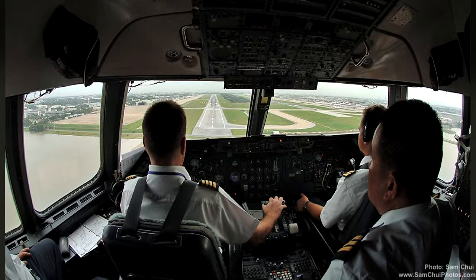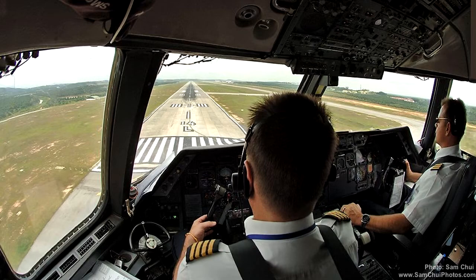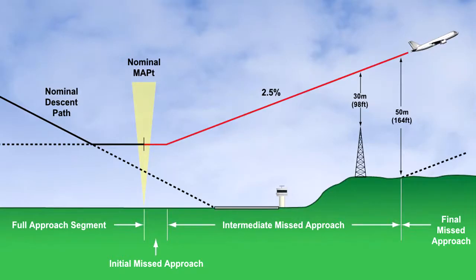In the event of loss of glide path during the final approach on an ILS precision approach, the approach will become a non-precision approach and have to use the OCA or H published for a glide path inoperative circumstance. In any event, the final approach segment ends either at touchdown or at the missed approach initiation point, if a missed approach is flown. When determining the decision height for an ILS approach, the obstacles in the approach path and missed approach areas, along with the constraints of the ILS installation, are considered.